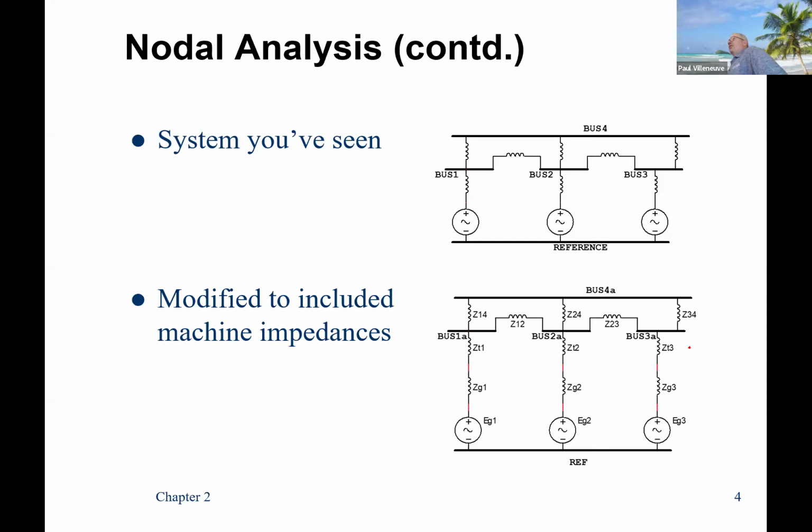So if you put a dead short circuit across a 12-volt source, if it's ideal, it will generate millions and millions, an infinite amount of amps to maintain that voltage. Can that happen? No. So any real world voltage source, the way you represent it is with an ideal source, as shown here, and an internal impedance, which limits the output of the machine.